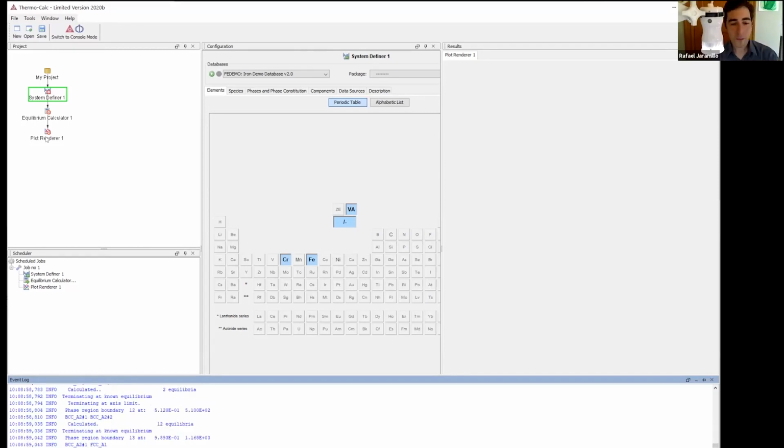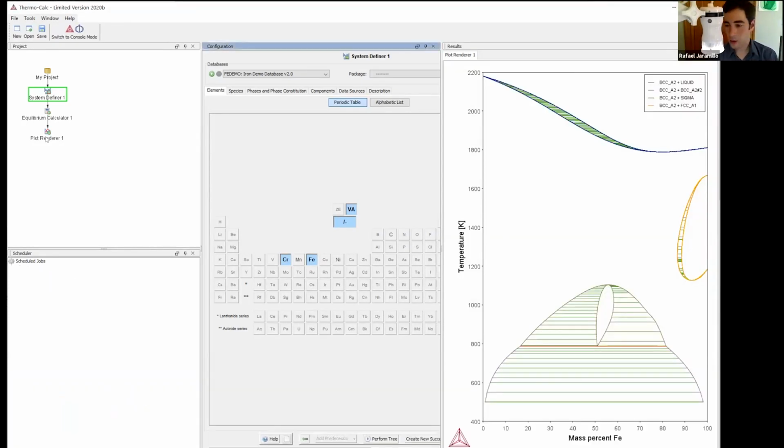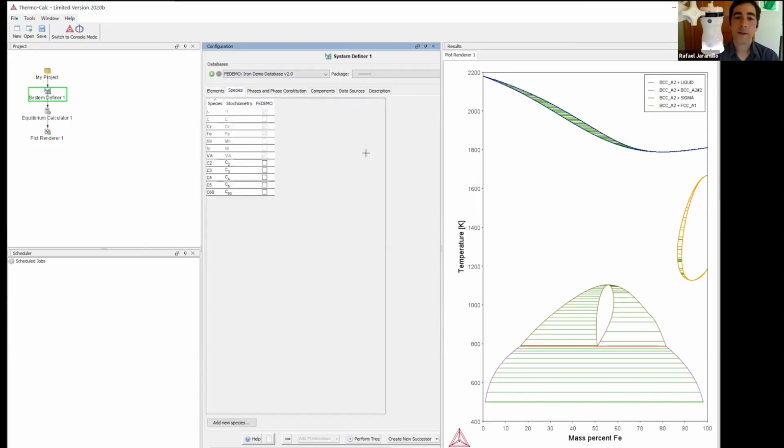So what it's doing is it's calculating the Gibbs free energy as a function of composition and phase. That is, it's drawing those free energy composition diagrams. And then it is doing the taut rope construction, or if you like, the inverse hull construction, and finding all the tie lines and coming up with the phase diagram. Okay, well, that's nice. But I'm going to simplify this. I'm going to reveal the hidden spinodal.